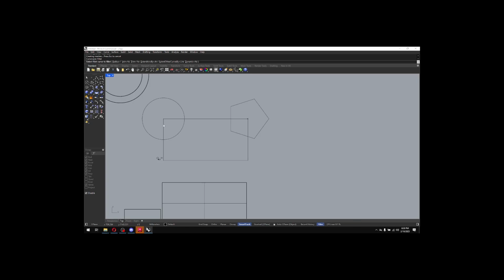All that's 3D. The regular fillet is going to be for your 2D line work. So if I'm in fillet, you can either click on these options up here, or I can say, okay, these were 20 by 40, so let's say I want a 10-foot radius.